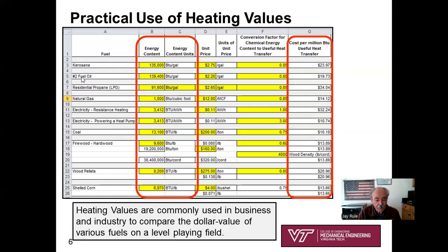And you might be studying which one of these fuels should I buy if I want to generate heat. This is where the higher heating value and lower heating value really come in handy, because engineers are in no mood to spend hours and hours going through that detailed Chapter 13 first law analysis to determine the heating value for a certain proposed situation, when in fact you can get a tabulated higher heating value or lower heating value. Tabulated, if you look closely, it'll say for complete combustion.